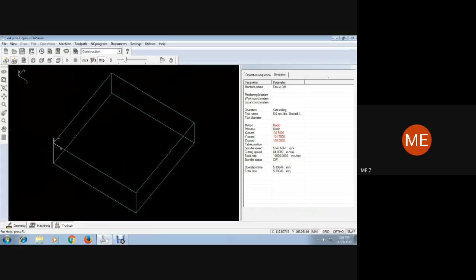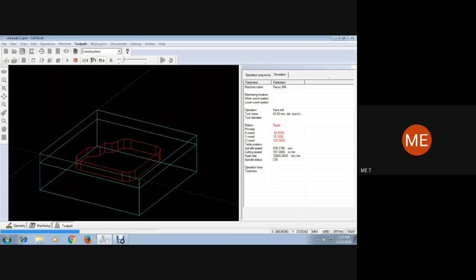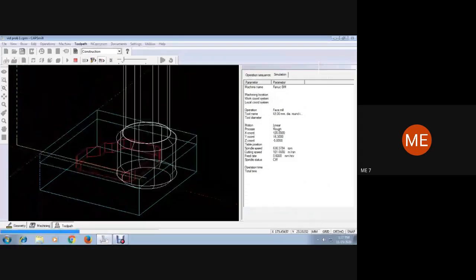We'll see this in a slower motion. Yes, this is the end milling that has to be performed. You can see that the face milling tool shown on white color lines landing up near the workpiece, and this particular portion over here on top for about 10 mm is what is going to be removed.